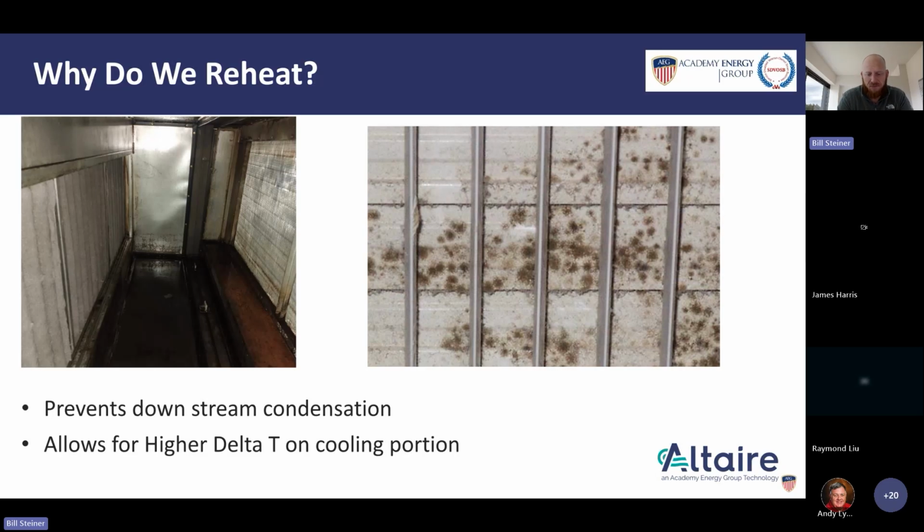You might be wondering, well, hey, I'm bringing this return air in. I shouldn't be fully saturated. That's true if you have fully mixed your air. And even in scenarios where we're using air blenders or you've got shelf mixing or some sort of dedicated way to make sure we're really mixing the air, it's never truly 100% that you've fully got complete mixtures, and you're not going to have a pocket somewhere in that airstream of the fully saturated outside air. So that is why it's really important to reheat as soon as possible.